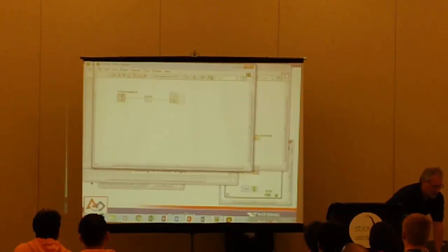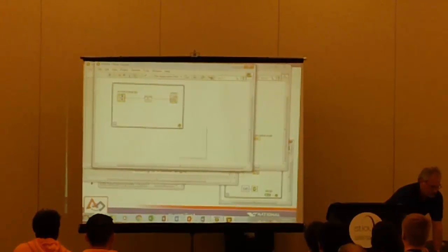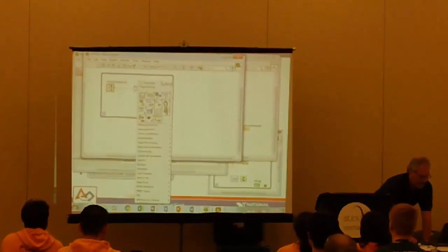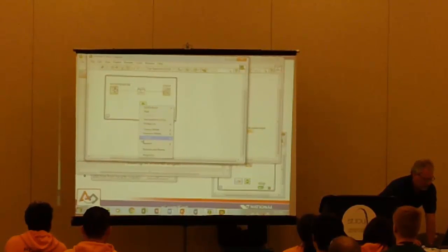And then just for completeness, I'll go ahead and put a loop around this to show you it's pretty quick to create a while loop. I'm going to create a control for a stop button. And I'm going to add a little bit of timing in here so this doesn't run so it only runs every, let's say, 20 milliseconds. I don't want to tell it about speed.